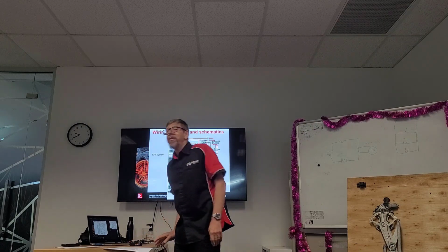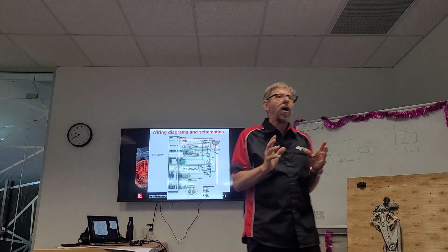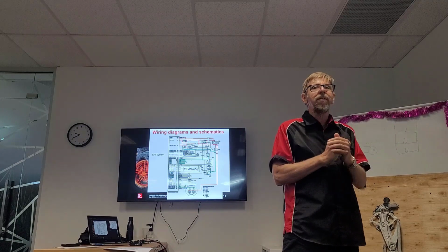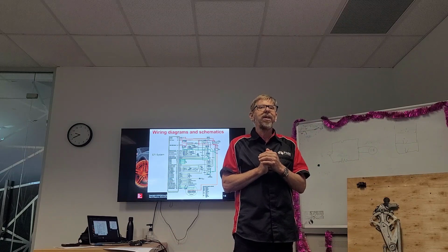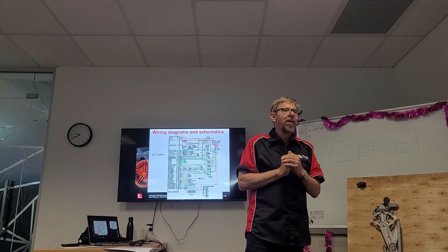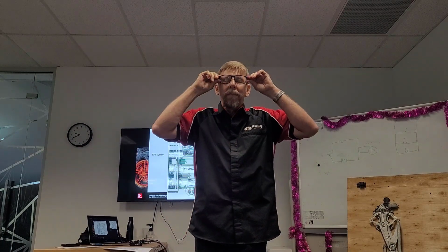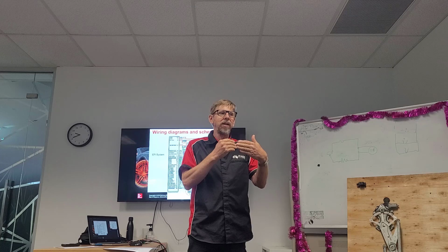This time I want to look at my DIS. What's DIS ignition? DIS is distributorless ignition system. Okay, DIS. In the time that we had a single coil, we then went to three. So it's a 6-cylinder, 3 coils, a 4-cylinder, 2 coils. They're called DIS, where they didn't have a distributor, but they had waste spark ignition coils.